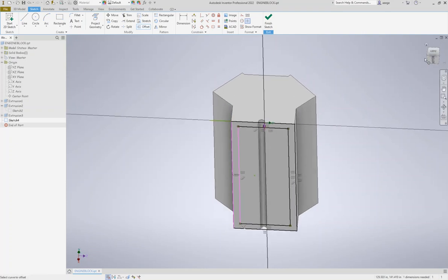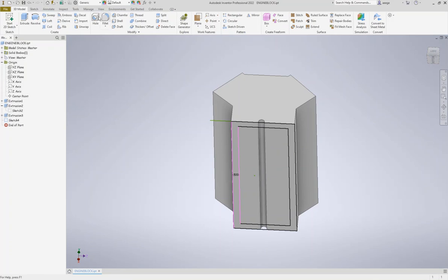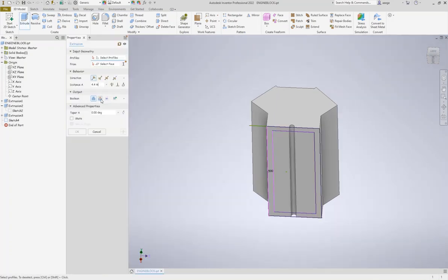All right, is everybody clear on this? And finish the sketch. Select extrusion, select cut, and select the area. Going to go this way. How much is it going to be extruded? That's a question we should answer right now. I will go 1.57. So that's 1.57. Extrusion, and enter.